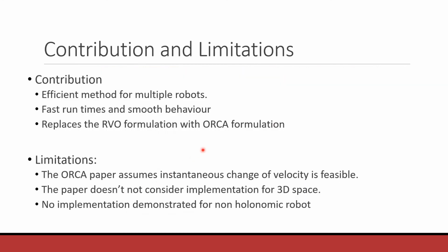So the paper contributes in formulating an efficient method. It also exhibits a faster runtime and a smoother behavior than the normal RVO formulation, and hence it effectively replaces the initial RVO formulation. However, the limitations are that ORCA doesn't consider acceleration constraints again, so it's just assuming that we can instantaneously change our velocity at any time t.